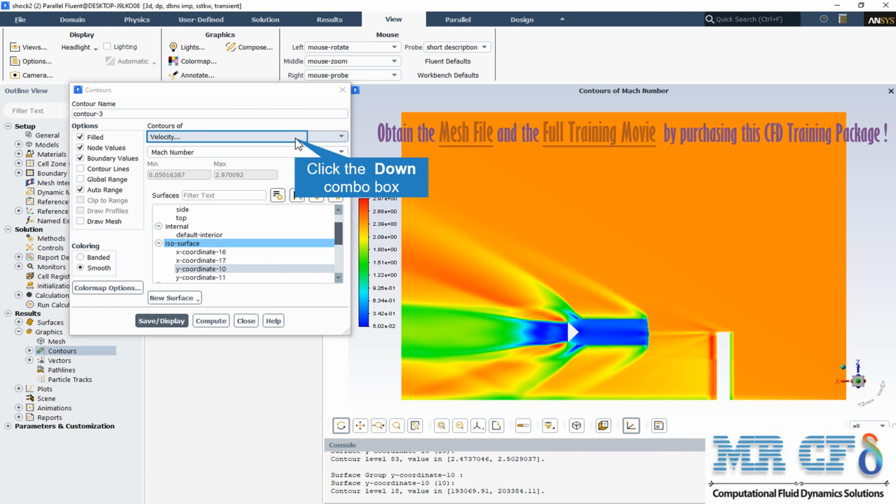As was mentioned earlier in the introduction part, shock wave occurs when a body is moving faster than the speed of sound in a fluid. Now in a subsonic flow, the propagating pressure waves have enough time to inform the upstream flow to change its direction in order to pass around the object. However, in a supersonic flow, the object is moving faster than these pressure waves and not letting the fluid change its direction.